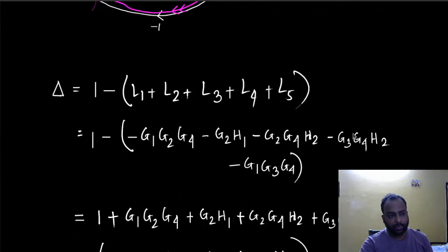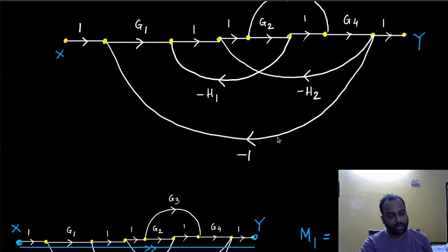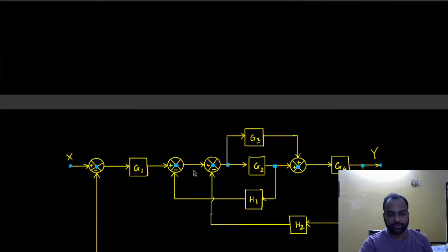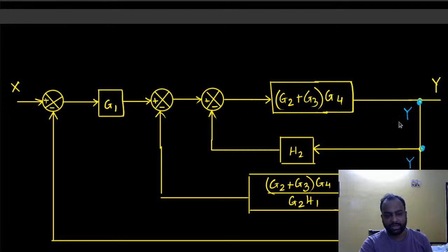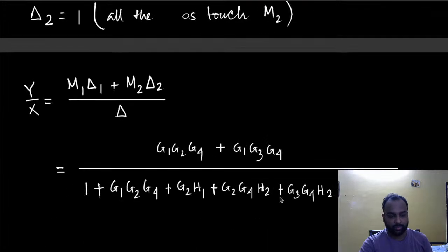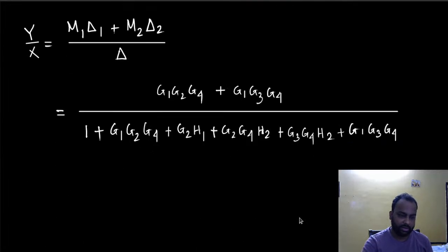Okay, so I would again suggest you solve this one and calculate the transfer function accordingly. Solve this one through block diagram reduction the way we did it. Do a feedback here, and again feedback, then cascade, then feedback. Do the simplification there, and you shall see that you would end up with the transfer function we have here. All right. So that will be the end of our discussion today.